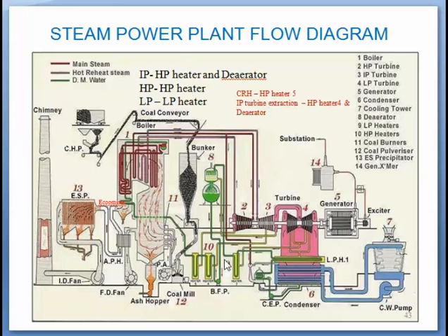For heating of the feed water in the LP heater, steam is bled from LP turbine and it is being sent to the LP heater for the heating of the feed water. During this process of heating in LP heater, the temperature of condensate rises from 45 degrees centigrade to 110 degrees centigrade. This heated feed water goes to deaerator.